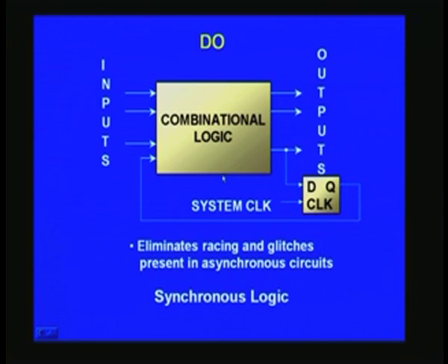And here you see that whatever is the combinational logic that you have inside, which will produce this output, will be processed only when the system clock arrives, that is at the rising edge if it is programmed for rising edge direction as such, and the Q output is naturally delayed by 1 clock pulse, because this will take effect for the next iteration, or whatever you call next processing, only at the next clock pulse.